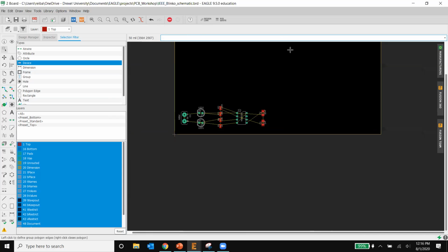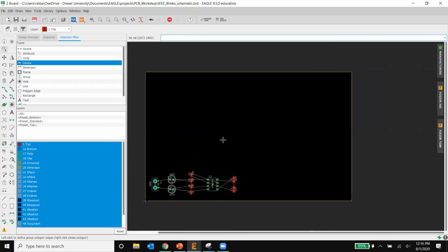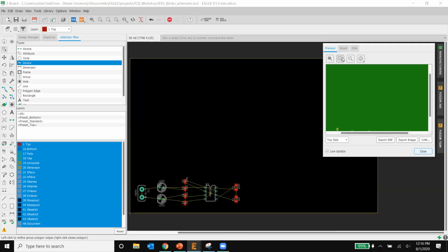Okay, now it looks good. Now if you go to manufacturing, you're going to see how it looks. A lot of things changed. You can see the copper wires on it, and it's going to print these white things. This is just the silk screen. This is just the naming convention, basically, that shows you where things go. Where you see this yellow thing, there's no soldering mask there, so basically you can solder there. Wherever you have green, there is a soldering mask, so that means you cannot touch the copper.